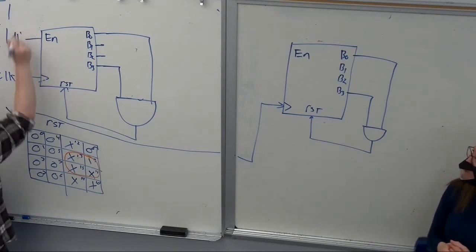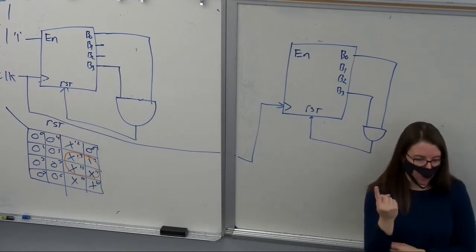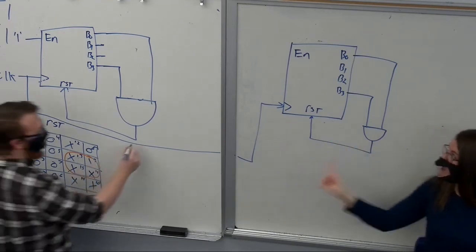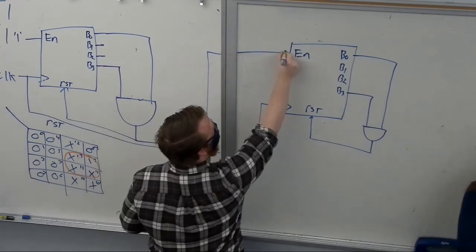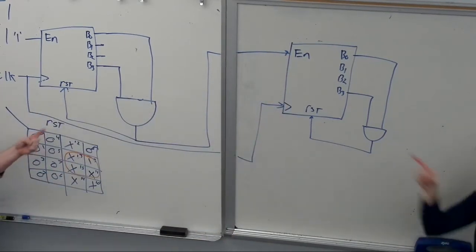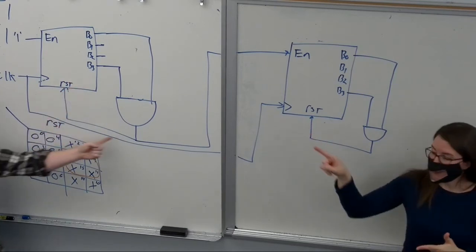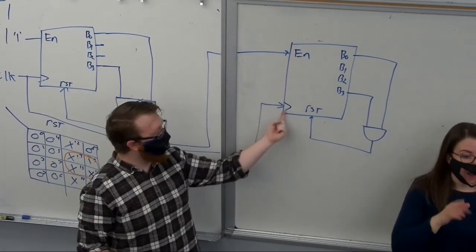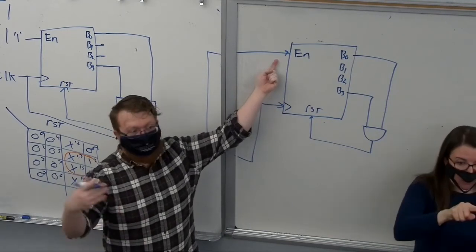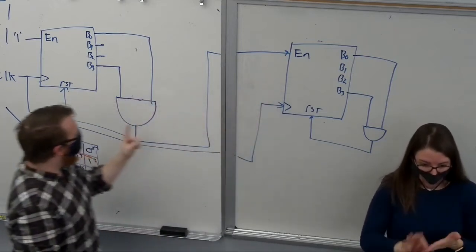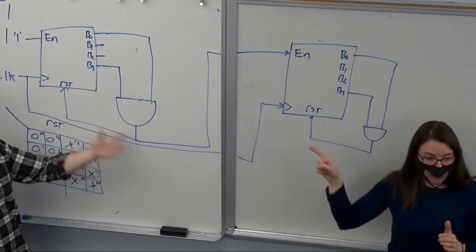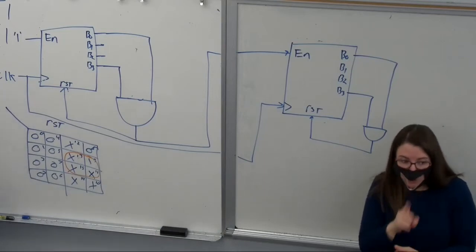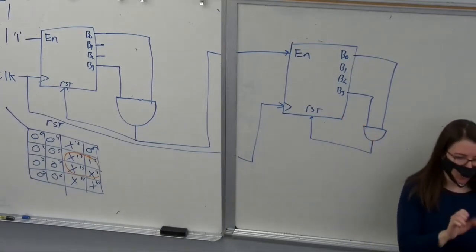So this enable, let's say, is just 1. It is always enabled. Would you feed the reset into the enable of the next one? Yes, exactly. So what this says is when this one ticks back over to 0, that means here is a 1. This one says, oh, look, I'm supposed to count once, right? Because the clock edge will hit, the enable goes on, it counts, but as soon as it's done with that count, that means this one has moved on to the next number. The output of the AND gate is no longer true. We're no longer enabled. Everyone see that?